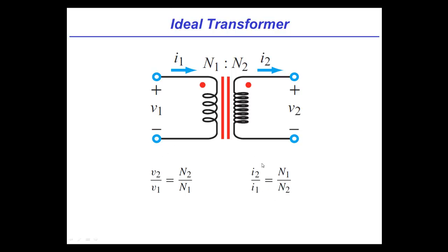That makes it very good, right? Because if I have a load here that is designed to run at 12 volts but draws 1 amp, the current that we draw from the 120 volt source will be 0.1 amp. That makes sense. That's kind of nice. That's why these are great. They're very, very efficient. So you can get current or voltage amplification effectively, at the expense of the other. That's right. Okay, fair enough.